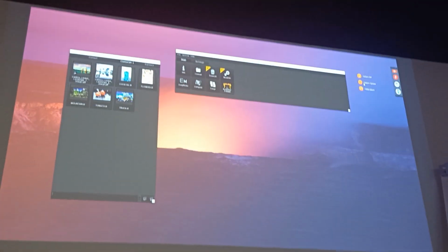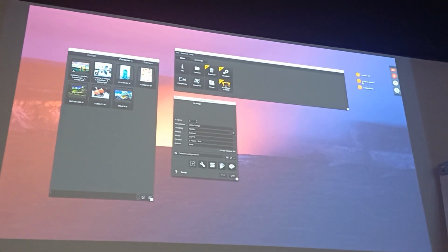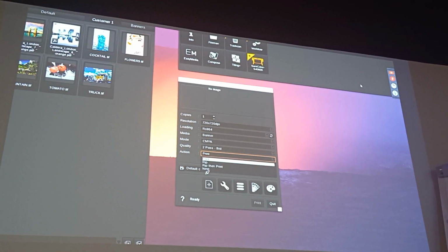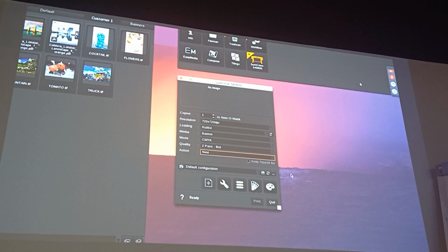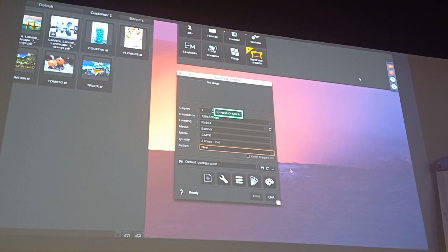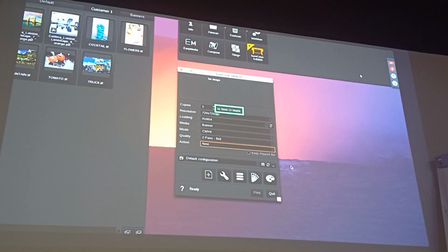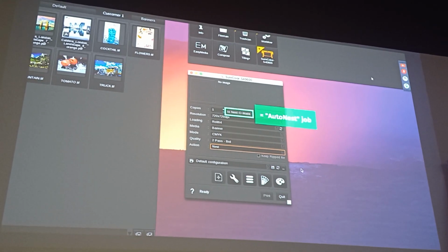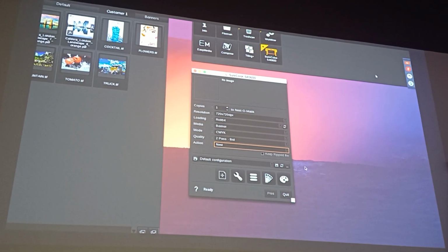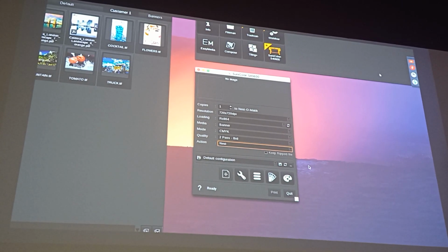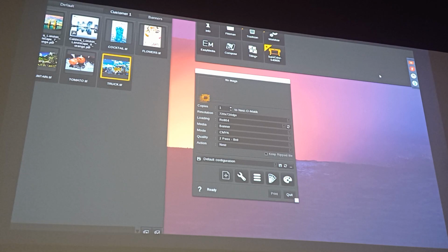To benefit from Nestomatic, simply open your driver, then select Nest from the Action scrolling menu. At this point, we are not going to rip or print anything. We will simply queue images to print inside one single pending job in the spooler. This job is called AutoNest. Once the nesting is long enough or big enough, we will launch the ripping or printing process from the spooler. Enough talking, let's do an example.